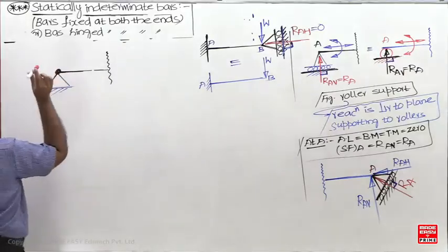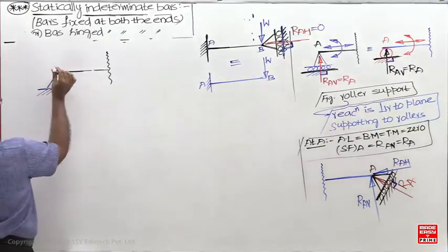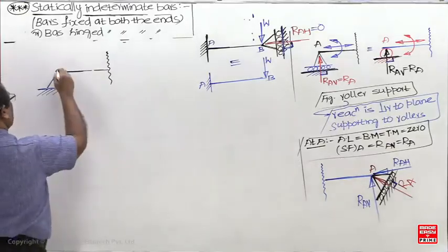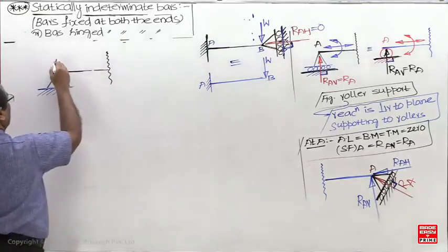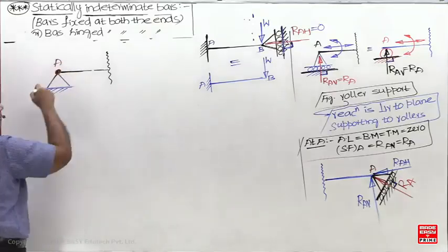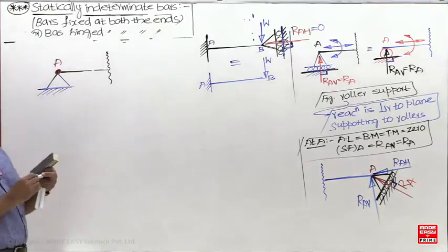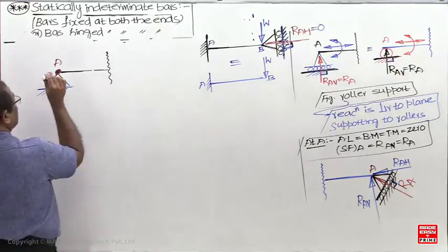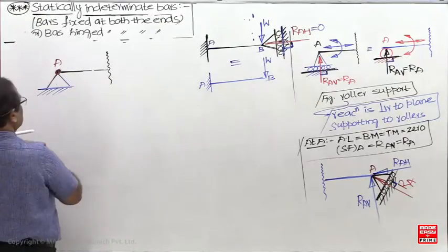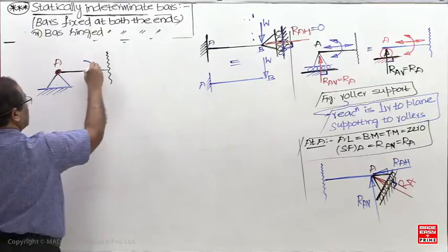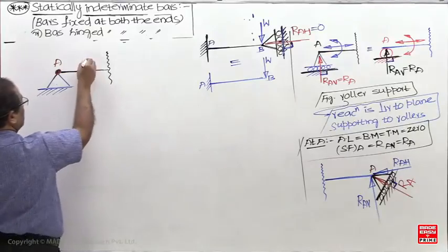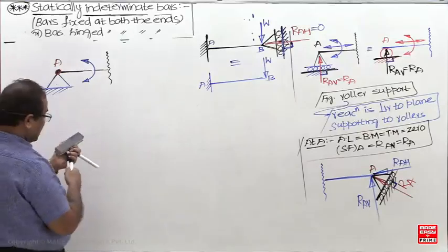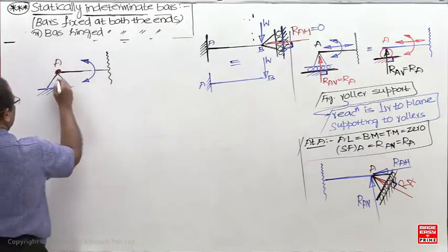That is what this marker is. Where can you see this marker? In the side view. In the front view, it becomes a dot. So this is called a hinge or a pin. Now if I apply a load, this pin will restrict the axial motion. This will permit only rotation. Only rotation is permitted. Now which motions are restricted? Vertical and axial.